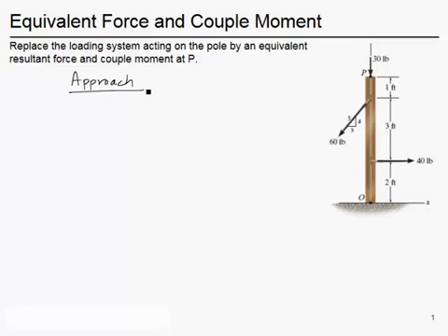So there's really only two pieces to this problem. The first part of the approach is to find the resultant force, Fr, and the second part is to find the resultant couple moment, Mr. And this is going to culminate at the end with a sketch of what this looks like. But you can think about these equivalence calculations as being like vector summations. And as you'll see as we go along, these vector summations follow the typical rules of vector summations. We just have to be careful with the usual things like angles and sines and the like.